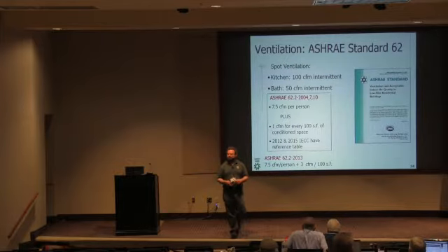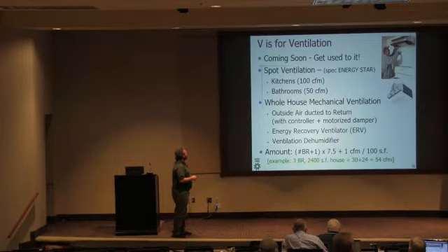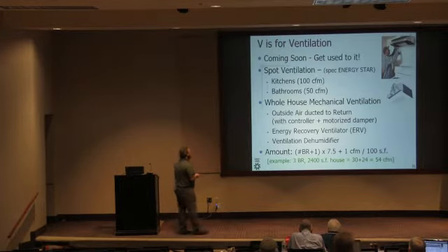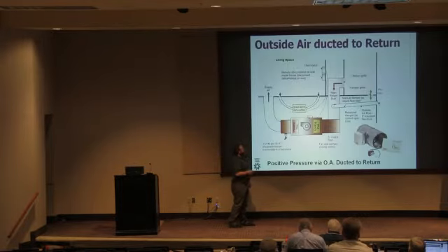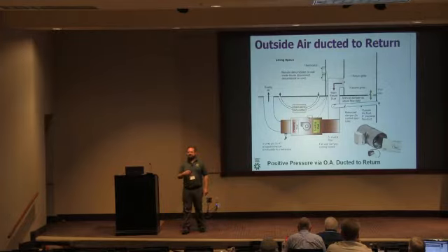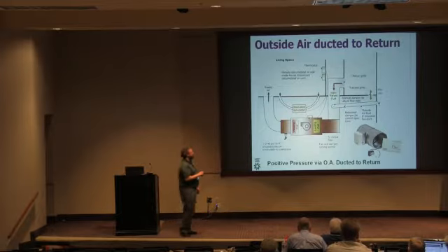How is the ventilation air introduced? Great question. There are a couple different strategies. But essentially, the most common strategy we see for introducing mechanical ventilation into the home is this: a rigid duct, 6-inch duct typically, runs to the outside, ducted to the return side plenum.